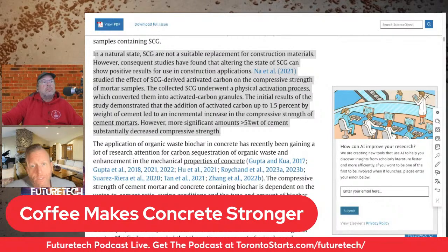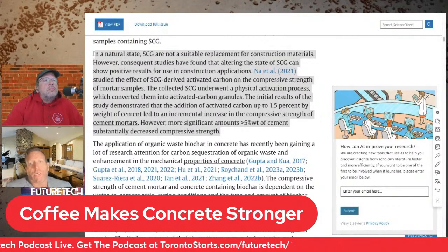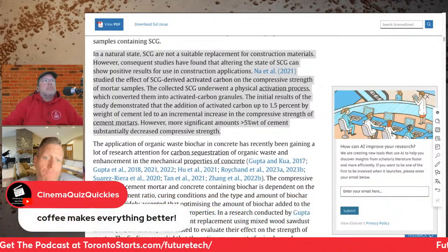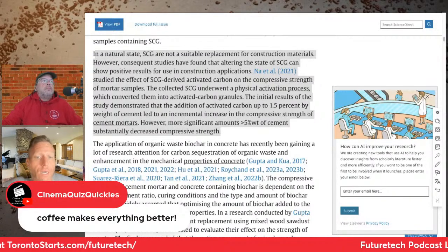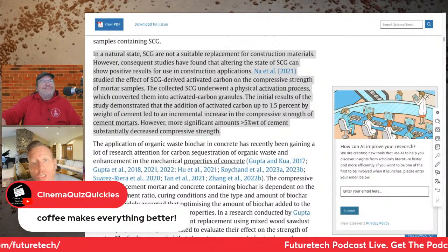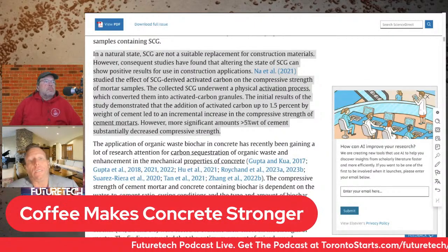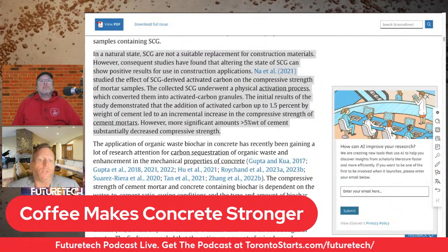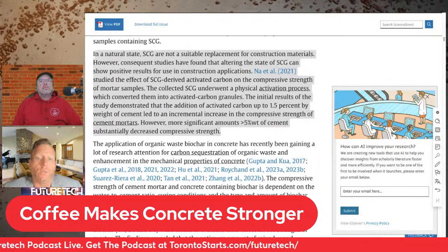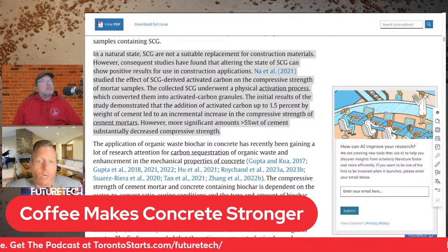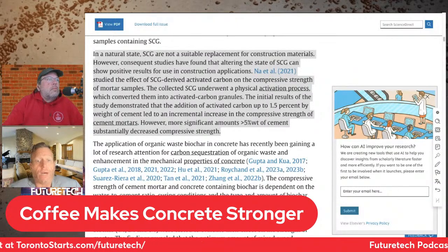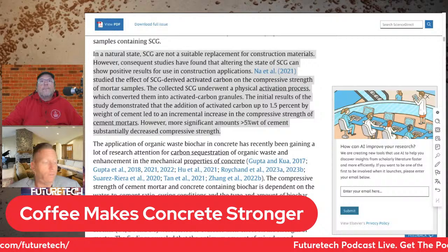So cost analysis is going to be needed as well for the biochar production and concrete customization. It could be more expensive, but they haven't looked into that yet. The other thing is, can changing the curing behavior complicate the pouring and the setting? They have to look into that too. And then there's potential concerns with odor or volatile organic compounds from the biochar. So it may interfere with the use of other cement additives as well.